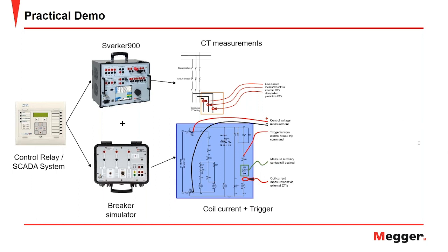So yes, you can do it, but I would advise you to do it with the conventional test rather than with the first trip. The first trip, just do the coil currents and CT currents, since these you can connect to without worrying about anything. But for the motion, to be honest with you, from a safety point of view, I would not recommend doing it while doing the first trip test. But during the conventional test, yes, I will definitely recommend you do that. But don't forget to release all the stored energy, then connect to the mechanism using the transducer, for added safety as well.